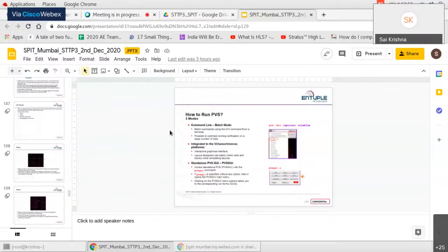And then you go for physical verification, where you perform DRC, LVS, ERC, etc. And after you rectify your physical verification, you will once again check your timing and power analysis. Only if no new violation is induced, you will create a GDS file of the design and send it for fabrication.